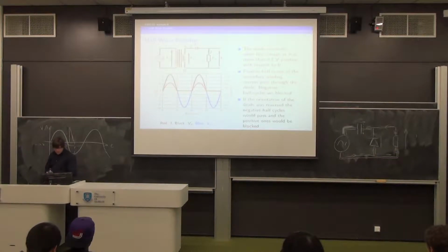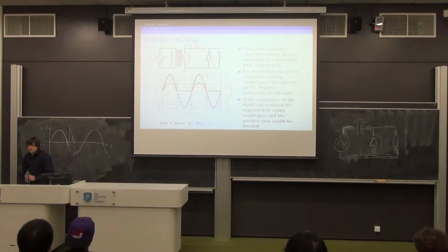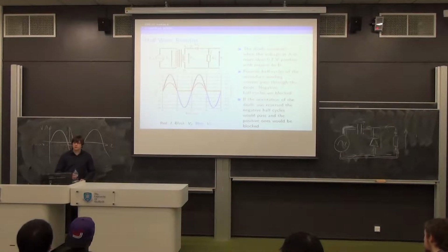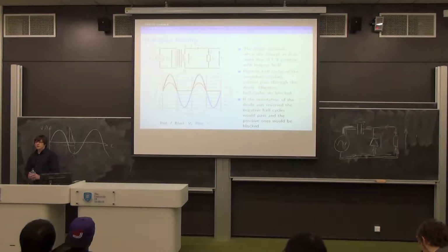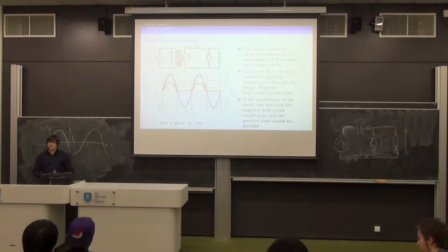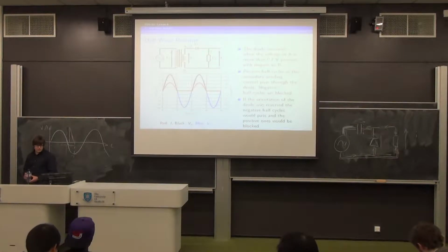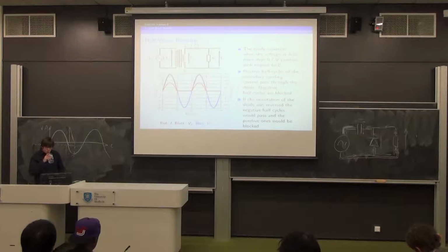So let's talk about some rectifier circuits for a bit. I'm not really worried about what happens inside the transformer. You can think of it as a black box where you put one voltage in with some current and you get another voltage out with some current, and the current times the voltage adds up to the current times the voltage. That's fine. I'm not going to bother with how you construct a transformer or what the flux should be or turn ratio or any of that stuff. It's just volts and amps. And what we've got thereafter is a peak detector minus the capacitor. So we're down to just 2 components now. And the graph is below.